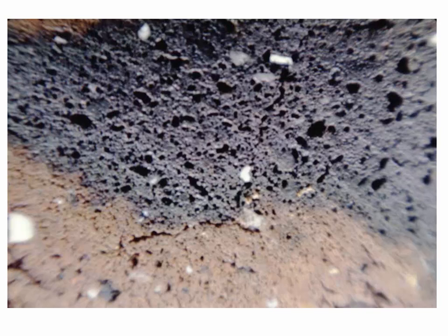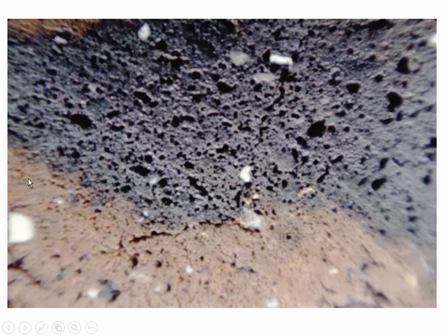It also has a beneficial ability to reduce the weight of the bricks, because the organic material, what we're zooming in on, it's little voids, where when you heated the bricks, the organic material burned away, and what's left behind is a more porous brick, which can be an advantage if you're trying to make lightweight bricks. Sometimes the sludge will be mixed in with the clay and the water at a brick factory, and it's extruded and then baked, and it just leaves behind a very porous brick.